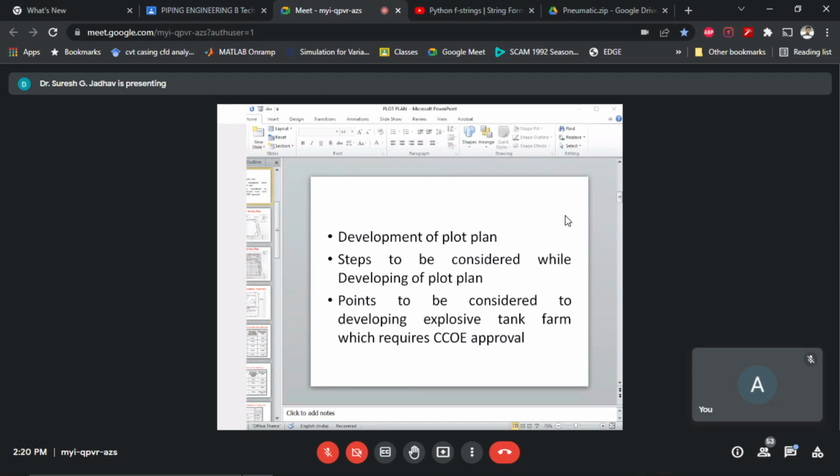site. However, for excluded petroleum class C, it can be 600 millimeters. Class A and/or Class B petroleums can be stored in the same dike enclosure when Class C is stored together. All safety stipulations applicable to Class A and Class B shall apply. Excluded petroleum shall not be stored in the same dike.